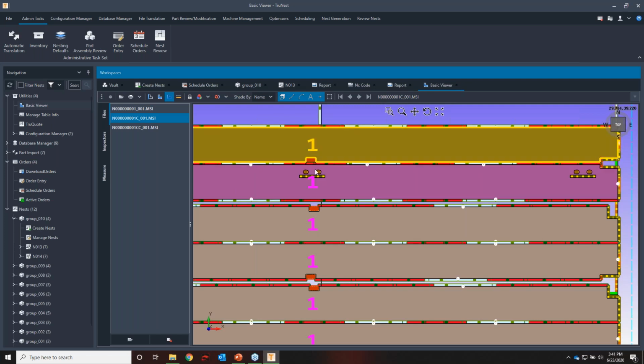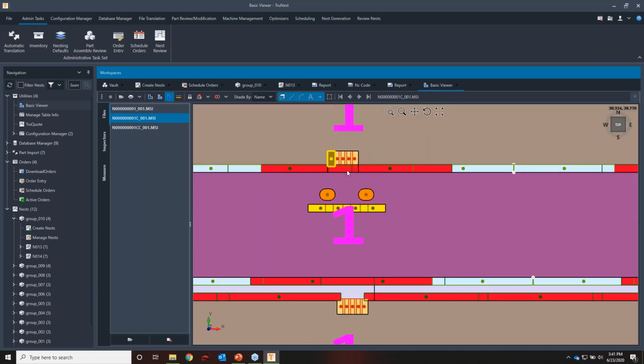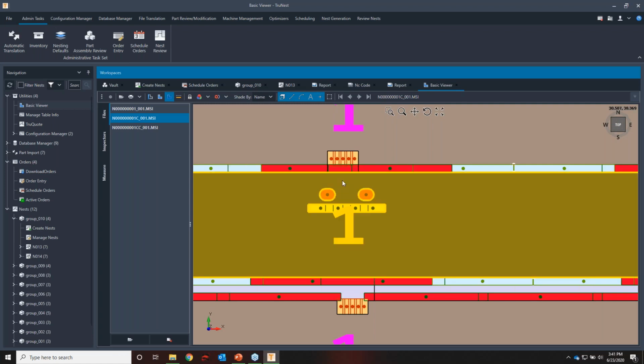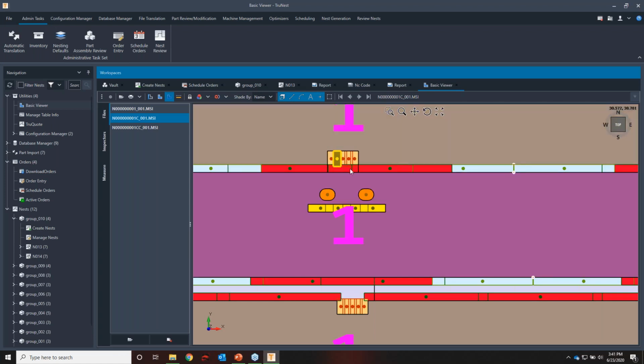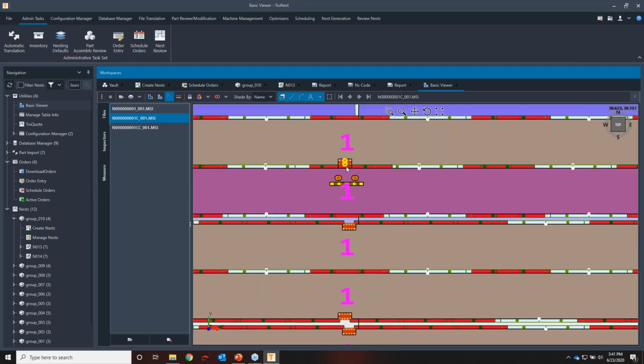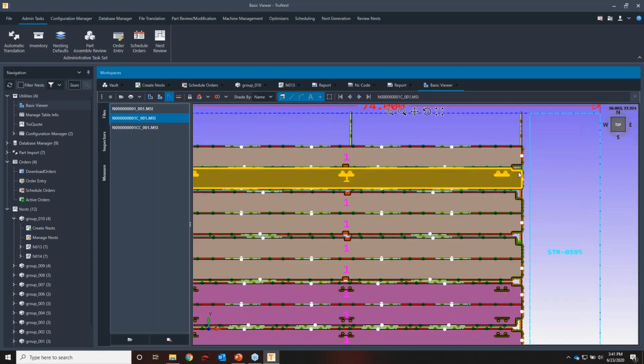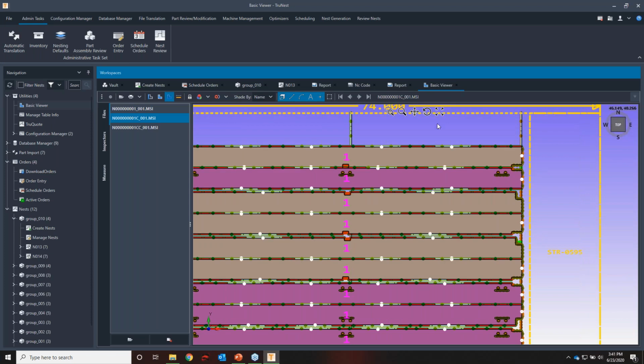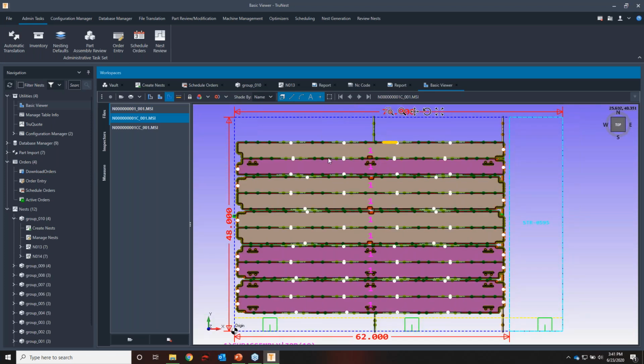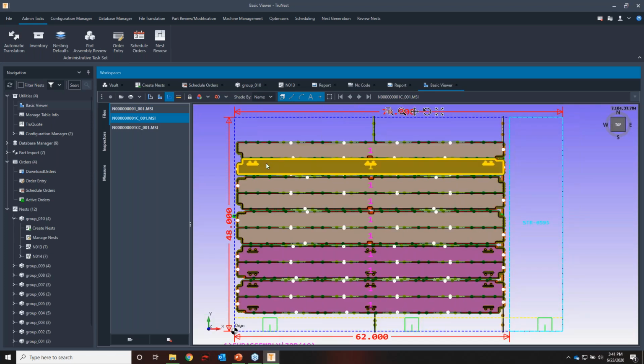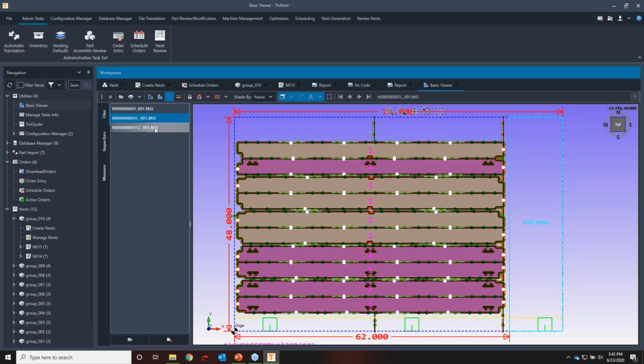So in this case, this would be an area, because we merge these two parts together, that we need to fully destruct and make sure it's fully destructed so we don't get any floating pieces or material in those parts. So in this case, just from that, we actually save about 6% on the amount of hits for these parts, just from a limited common line scenario. So in this case, it's probably about 30, 40 hits on the machine just by doing this process.